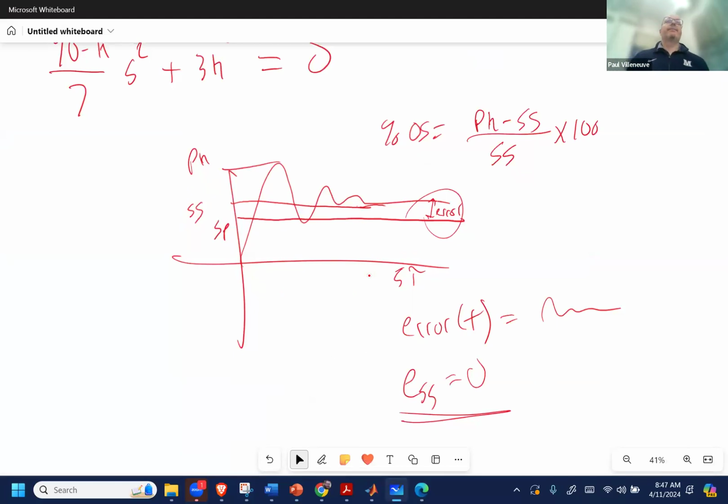Now what do you do with the pole? That's just your final answer. You need to calculate your value of K. So it calculates the value of K, and then it just tells you what the poles are, so you can check by hand if that is a satisfactory result. The poles you don't need anything with. Instead of having to plug it into your characteristic equation or your open loop transfer function, you just know what the poles are going to be at that value of K. So it's more information than what you need. You just need the value of K, because that's what you're designing. You're designing a system with a value of K, and then the poles are whatever they need to be to meet the design criteria. But K is ultimately the only thing you can vary.